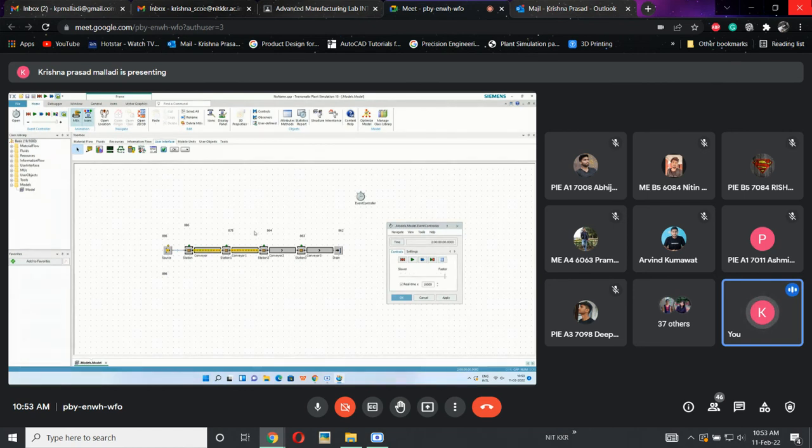Okay, so whenever you are creating a model, try to add this also, so that there is no need of entering into statistics and checking the properties each and every time. If you use this directly, then whenever a part enters here, see, reset the simulation, whenever a part entered, automatically it will be shown as throughput. The next machine is 0, so this part will enter into this machine, throughput 1, here throughput is 2. The parts entered into that machine will be visible here. You can calculate at the end of the process, even seeing the process running. Maybe after 10 hours I want to stop, at 11 hours 50 minutes, what is the throughput for each and every machine, that I can directly calculate by using these display icons.